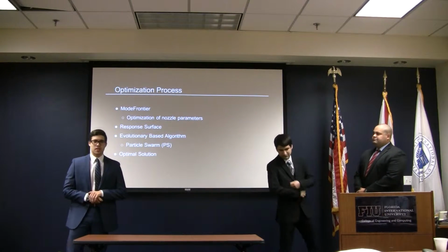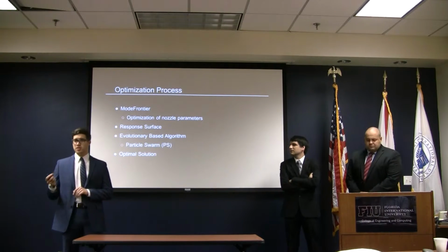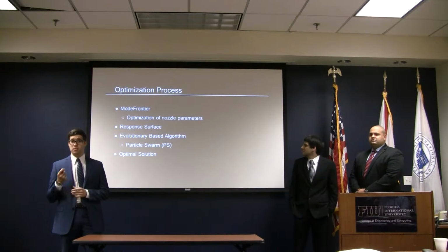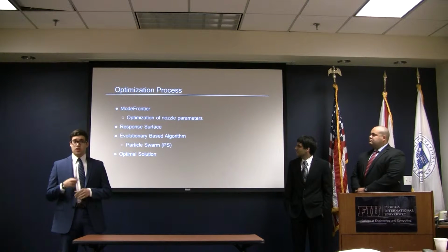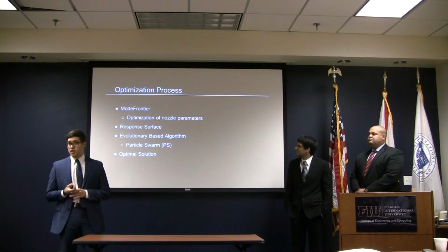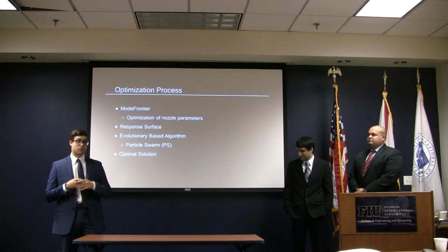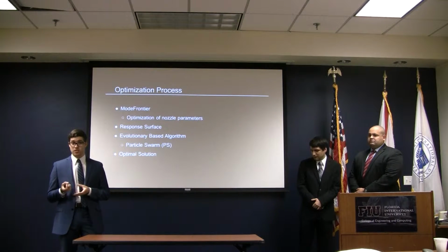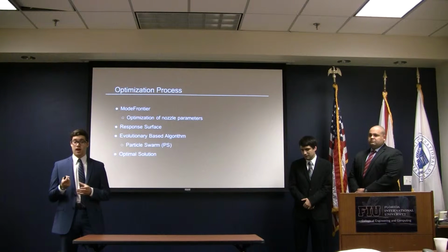For the optimization section of this project, we're going to be using modeFRONTIER. It's commercially available software, and we're going to use it to meet all of our optimization goals. To decrease the computational time, we're going to generate response surfaces using radial basis functions, and that will greatly decrease the time of computation.